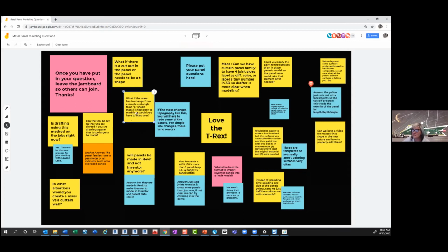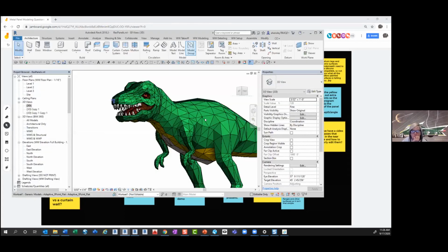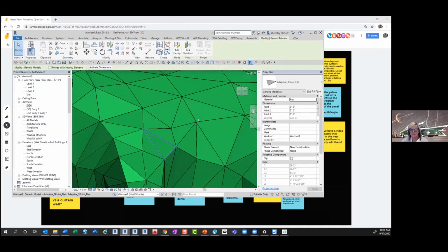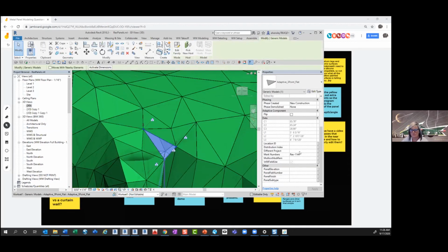I wanted to comment, Amy, on the first question that you asked with the cutout. There are two ways. With the fab number, we can put a 1N, like the takeoff team does right now, so that it denotes in the takeoff program to make that panel separate. Or we could create a notch that already exists in the panel, and that would also make it separate from the generic typical soffit panel. So there are two different methods for how you would do that.